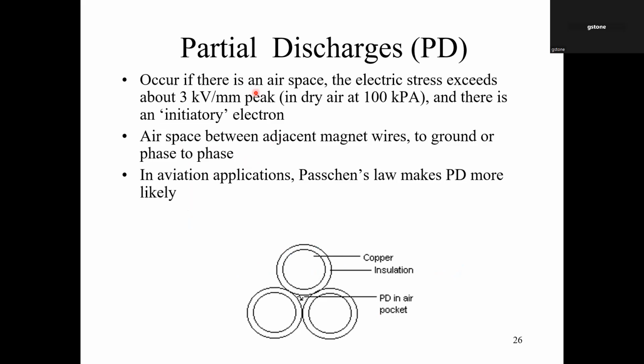Okay, so what's the consequence of this? Well, remembering that cross-sectional image I showed you before, let's take 3 turns, put them side by side. Here is the copper conductor from that magnet wire. Here is the polymer film. It's showing much thicker than it really is for that particular copper conductor. This is the turn insulation. And let's say we have an air gap here, which is not uncommon, or certainly was not uncommon back in the early 90s when problems were first being found.